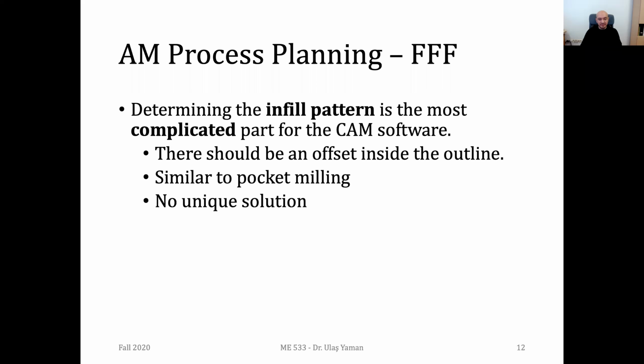And for the infill patterns, we don't have a unique solution. There are millions of solutions for a specific case. Depending on your parameters, your CAM software will calculate one and then represent that pattern with the help of G-codes. And we always try to find a continuous one, since if it's continuous, then you don't need to stop the extrusion and start it once again.